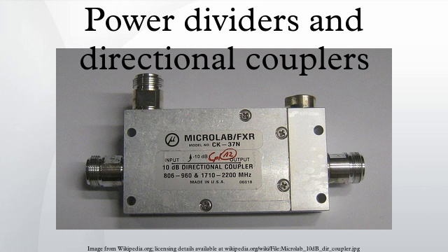It has two major drawbacks. First, the circuit will dissipate power since it is resistive. An equal split will result in 6 dB insertion loss instead of 3 dB. The second problem is that there is 0 dB directivity leading to very poor isolation between the output ports.